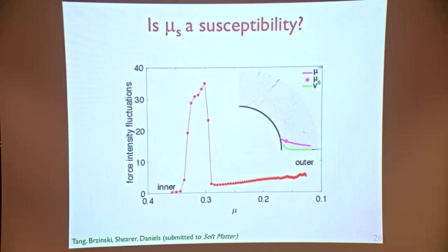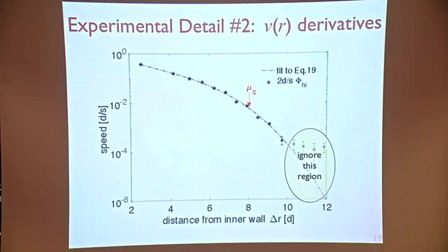They don't, actually. The green here is the velocity profile and the purple is the mu profile, and this is the point where it crosses mu s, and it's about partway down the velocity profile. I'll go back and show that to you. I had a better plot for showing that. So there's mu s on the velocity profile. Does it look special?